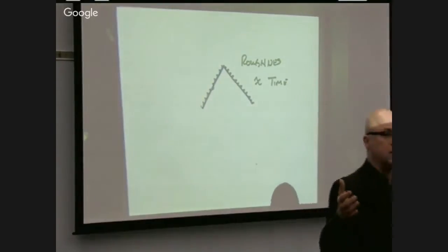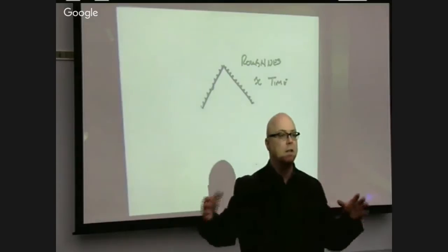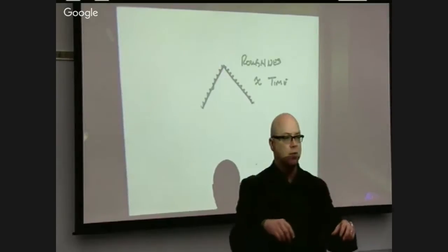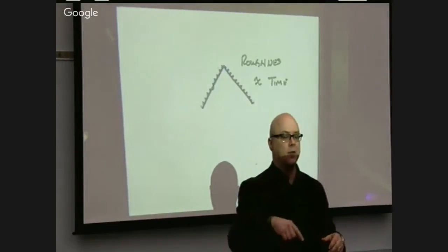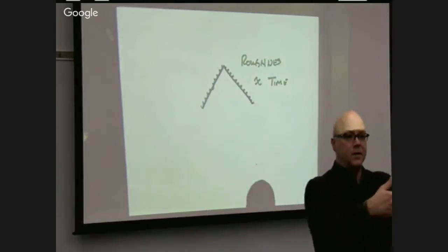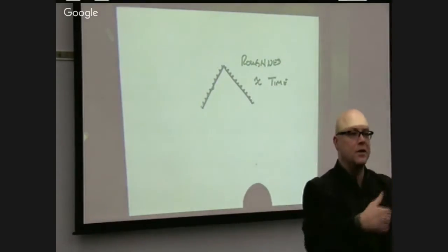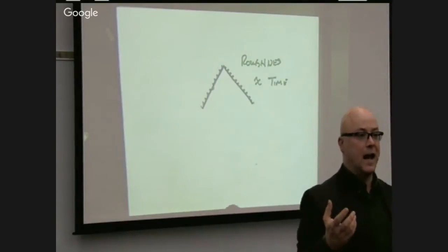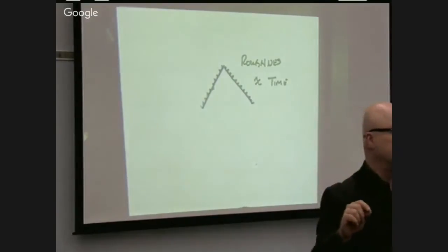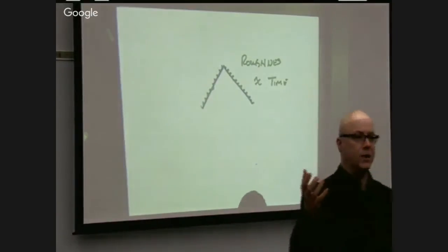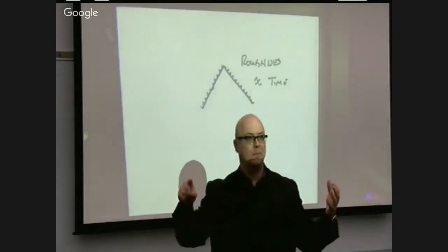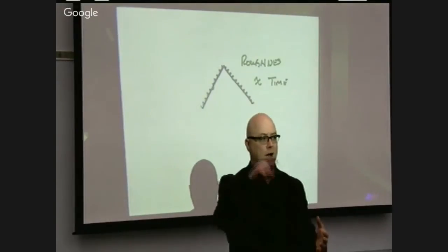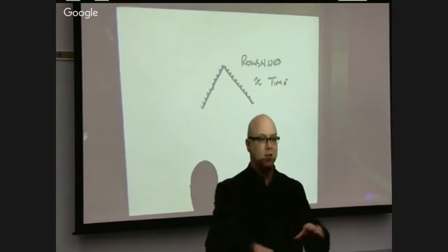Factory automation systems in the 1950s and 60s and into the 70s were all controlled by relays. There were relays all over the place that said when this is going to turn on, when this is going to turn off. A bottle would go past a light sensor or a touch sensor, and it would turn a relay on or off. The logic behind that is embedded in how you ran the wires. All of the logic of one of these factory control systems is in the wiring diagram. You connect this relay to this relay, with hundreds of miles of wire running around cabinets connecting relays to each other in order to control this.